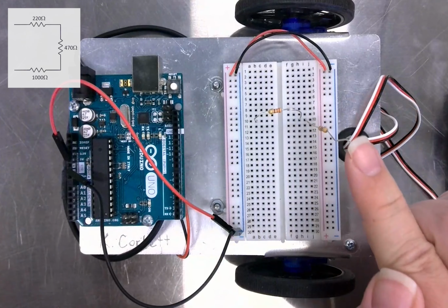So we have it plugged into some other row. So notice what happens here. Imagine if this was connected to power and current was moving through here, you'd go through this resistor, and because this resistor and this resistor are connected through that node, this row, row 10, it would go through this resistor and then go to this row here, row 16. And then finally, we're going to put our last resistor. This is the 1000 ohms. So we have our 220, our 470, and then our 1000 ohm resistor. I'm going to plug it into this row. That's the same end of where this 470 ohm resistor is connected to, so they're in the same node. And then it's going to be plugged into some random row on the breadboard.